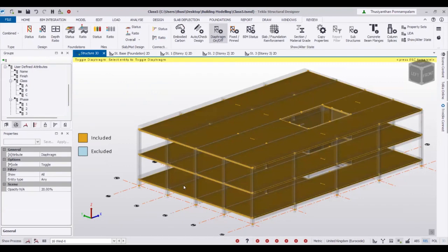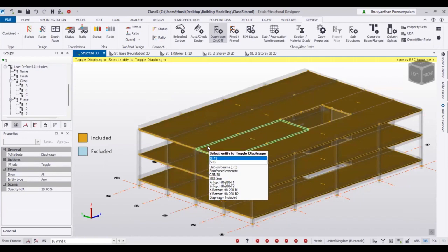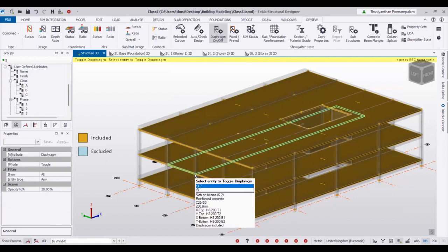So if you apply the wind load, it will be applied on the center of the diaphragm, right? That means if you apply along this width, it will be applied at the center of this diaphragm. So this whole plate consists of one rigid diaphragm. So each floor is applied at the center of the diaphragm. So that's the way we are going to apply the wind loads, right?